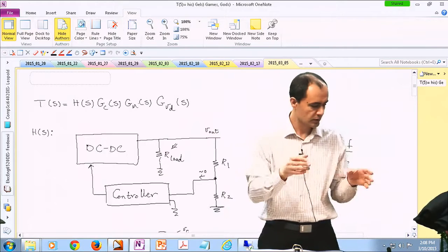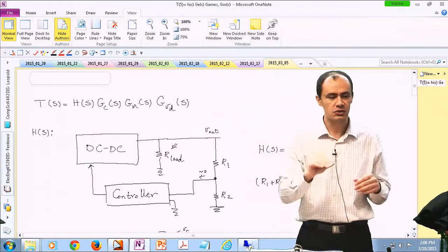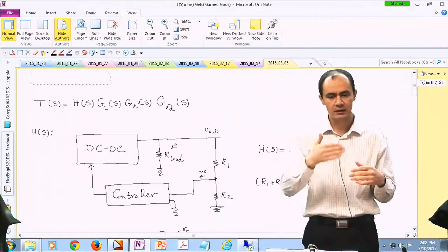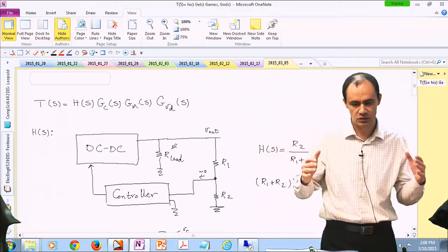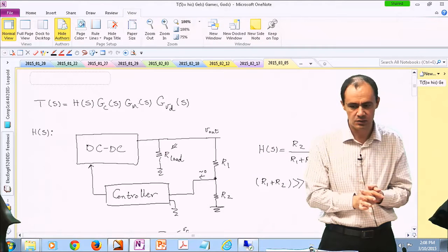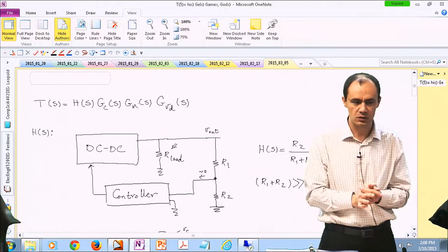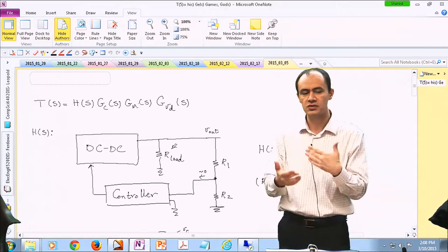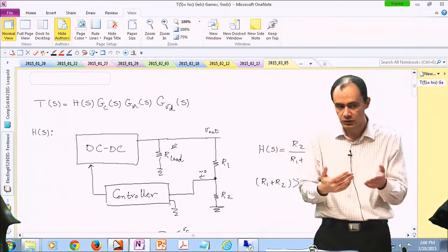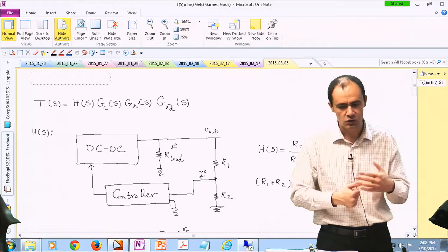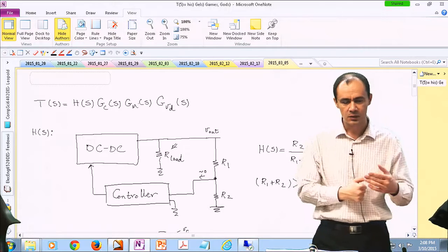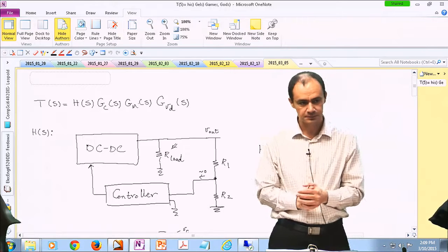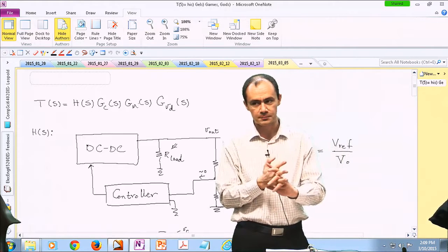And I can show you what's going to happen if I eliminate the zeros. If you just add poles, you're adding a lot of phase lag to the system, so you're making your loop gain very, very small, so the system gets sluggish. So zeros are like futuristic things. They look into the future. They look at the changes in the system, so they make the system fast. But at the same time, you don't want your system to be too fast, otherwise it's going to go unstable. All right, any other questions?